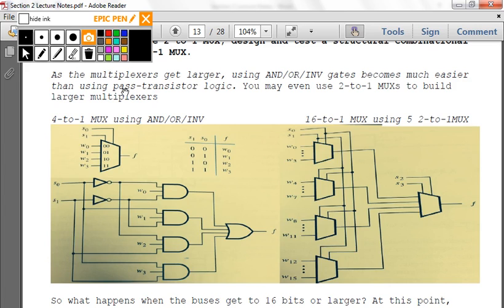Yeah, wasn't it like a circuit where you could open and close it depending on which state you wanted to use? Mm-hmm. And so one way we could do this is using multiplexers, right? I have two 32-bit values, and I want one of these 32-bit values on the output. So what would I design?